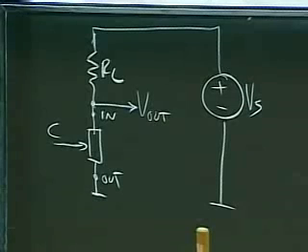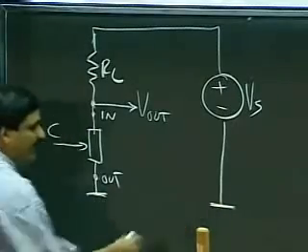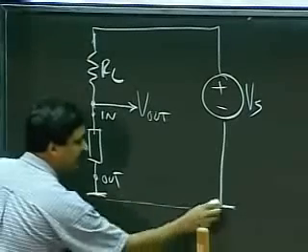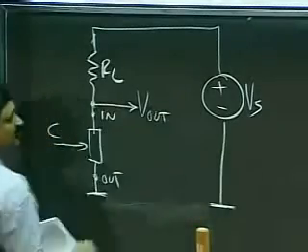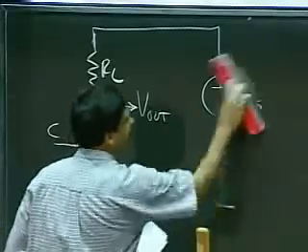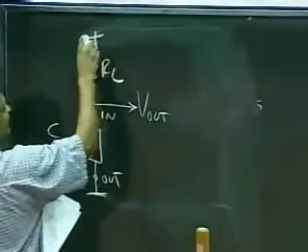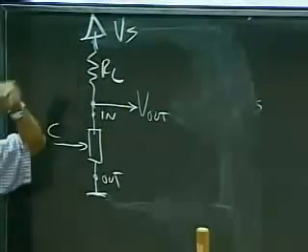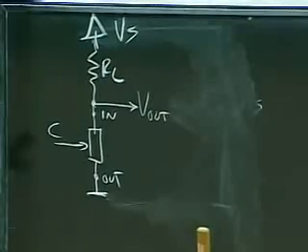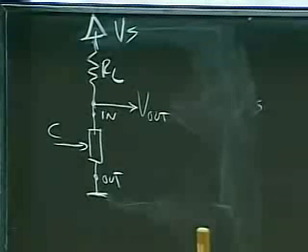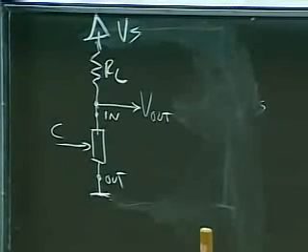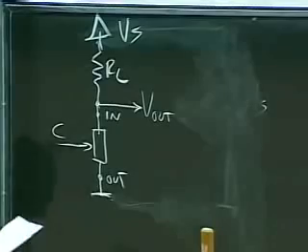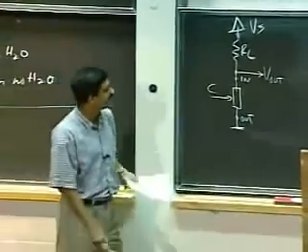Since this pattern occurs so commonly, I am going to create a short form. I have already created a short form, which is this ground node here. By putting grounds here, all I'm really saying is that there's a wire connecting these two, and that's my ground. So I already have a short form here. My second short form is when I connect a power supply to a node, then what I'm going to do is come up with yet another short form that looks like this. An up arrow with the voltage written there. This symbol simply says that this node is connected to a power supply, or a voltage source, with voltage Vs. So I just have come up with a slightly simpler representation for the little pattern that I have. Now let's take a look at the properties of this little system.